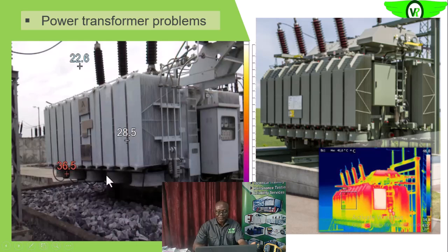So you see cooling fans, which are these two. When you take the thermogram, what you are seeing here is a normal thermogram. Are we getting it? This is the normal thermogram of a working transformer. Remember, as the insulating or cooling oil is heated up in the transformer, it absorbs heat, so that hot oil will naturally rise up. Are we getting why the cooler one will drop? Which means you expect to see a hotter signature on the upper part of the transformer, which is what you are seeing here, while the cooler ones will be coming down on the transformer. So this is a normal thermogram.